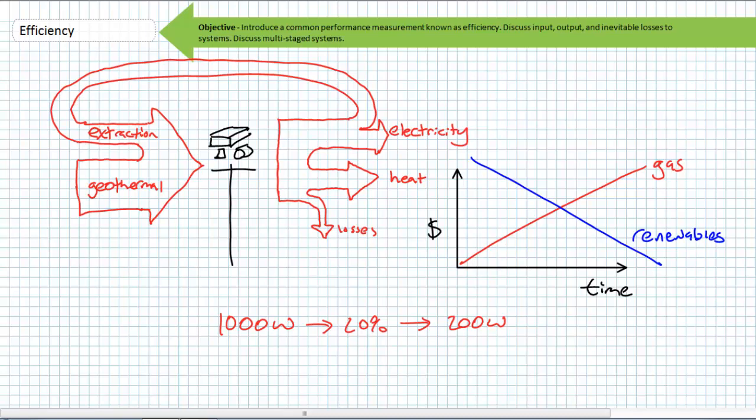In conclusion, this lecture presented the concept of efficiency, and we learned to calculate efficiency, input, or output. Additionally, we discussed cascaded efficiency arrangements and renewable resources. We learned that the efficiency of a cascaded system is a product of individual stage efficiency ratings and is always less than the least efficient stage. Finally, we learned that no system can ever produce output greater than its input, and we use this fact to check our work. You should be able to pick up this concept and run with it.